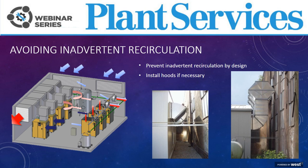So how to avoid it? The best way to avoid it is to use ducting and employ the points that we made earlier: thermostatic control, inlet and recirculation louvers, and also to have a prevailing direction of cooling airflow whenever possible. So cooling airflow from one side, hot air discharge to another. Having the majority of your airflow in one direction helps prevent accidental recirculation.